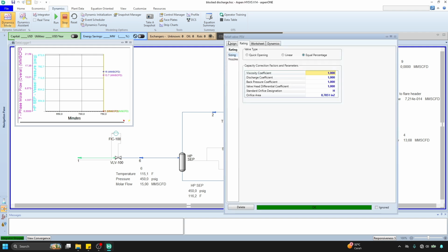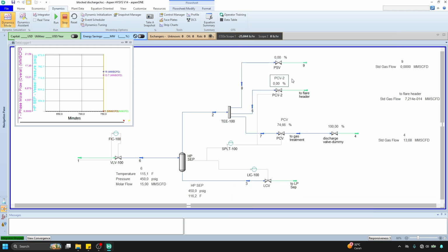And for the rating, I changed to H, and perhaps in this video we will also want to see what will happen if the pressure safety valve orifice is under design. For the first one, let's change the orifice design to H. Okay, select the one.